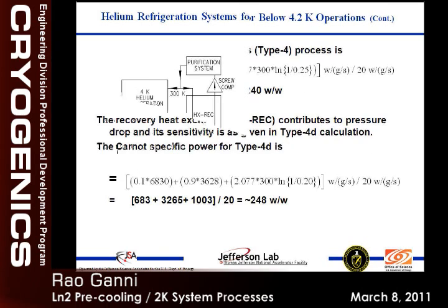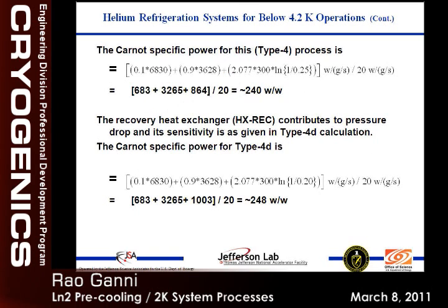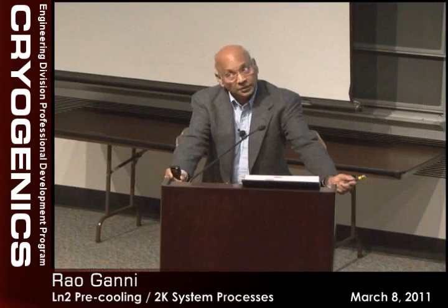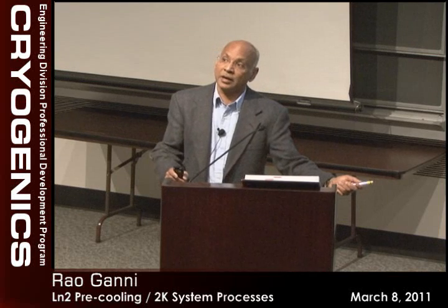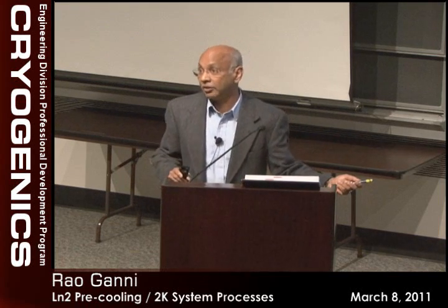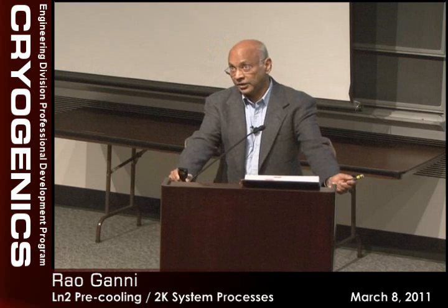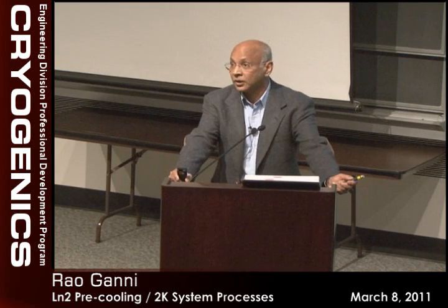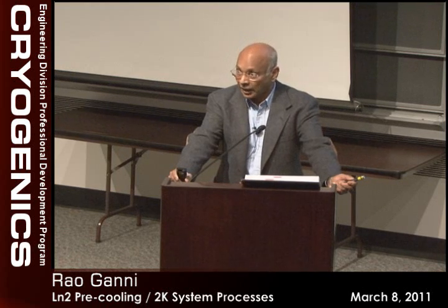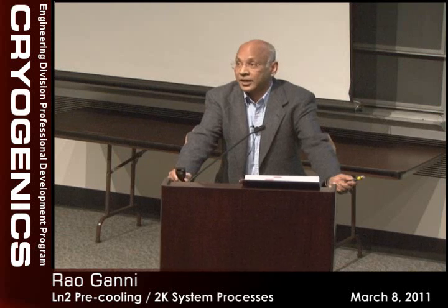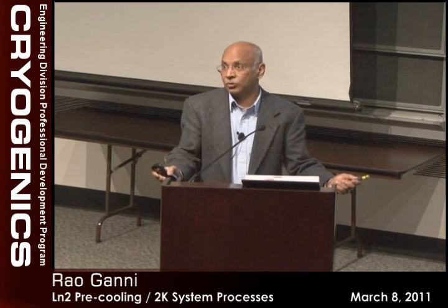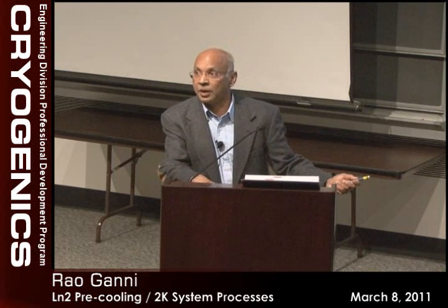As we look closely at our turn down, actually JLab turn down is not as bad. We were able to turn it down to 150 to 250. We vary our flow at CHL from 150 to 250 grams per second, down to 60% level. We may not be able to get to 40%, and 60% is not what we originally thought; we thought we could not reduce below 80%. But in practice, we have test data where we turned it down to 150 grams per second. So I think if we spend more time and research on how to manipulate the cold compressor inlet warm temperature, we can improve the rangeability of all cold compressors. But nobody is taking that direction and finding out those things; they are going into these hybrid systems.